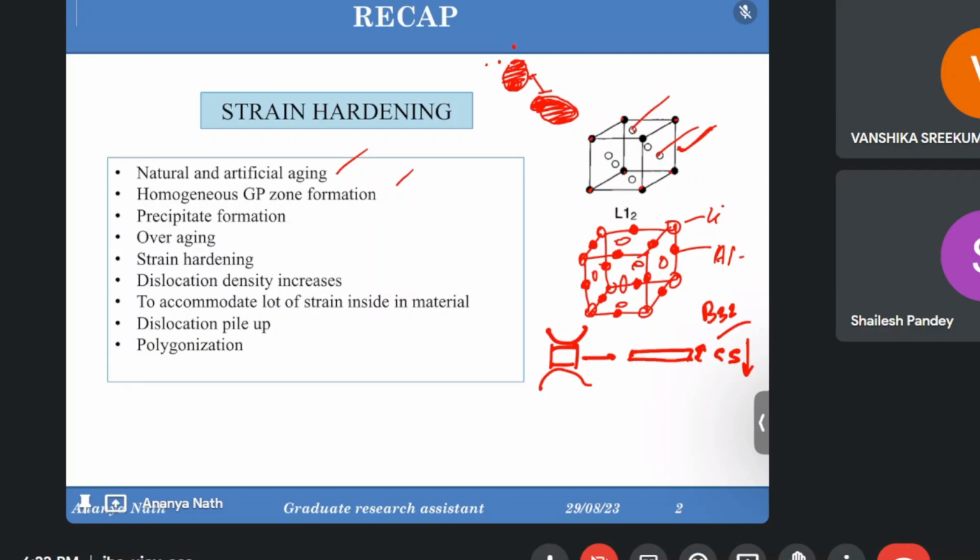In the slip system, the Burgers vector and these things are mainly responsible if we are talking about dislocations and their movement, because the dislocations really move towards the slip direction and through the slip planes. Every lattice has its own slip system, meaning a specific slip plane and slip direction, and only towards that direction and through that plane do the dislocations move, otherwise they do not move.